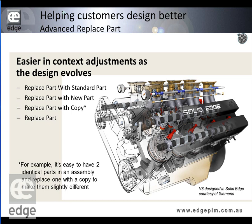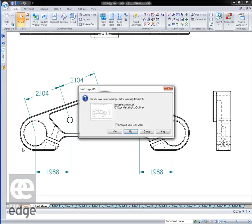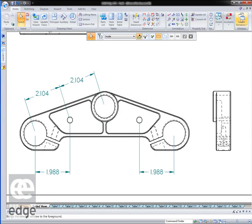But replace part with a copy is where we've got several parts instanced into the assembly. We want to change one of them, put a slot in one of them, or a groove, or change its length or something, but we don't want to do it to all of them, so we need to create a new part number, and it lets us do that. So we'll take a look at that. And switch over to Solid Edge, and cancel out of that.